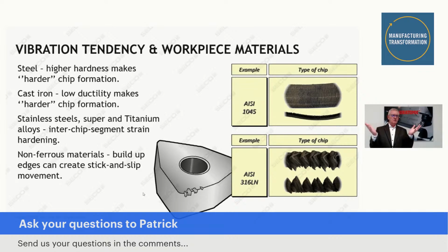If you say, yeah, but I don't have those tables, or I want to have more pragmatic approaches, there are 2 things, like always in machining: look at the chips and look at the used cutting edges. If you know what to look out for, that's for instance the technology we use in GTDA analysis, global tool deterioration analysis.